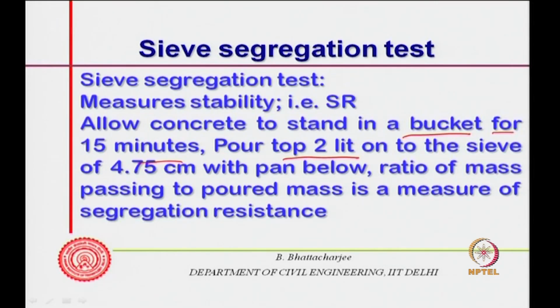Pour the top 2 liters on a sieve of 4.75 millimeter, it can't be centimeter, 4.75 millimeter, that is a sand size. That was a mistake.